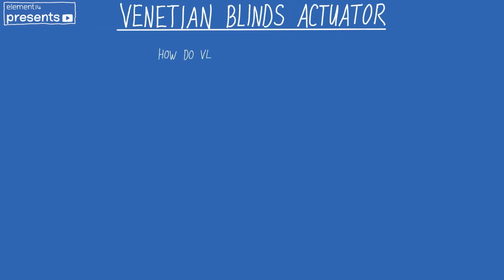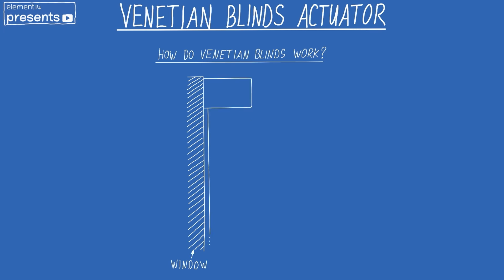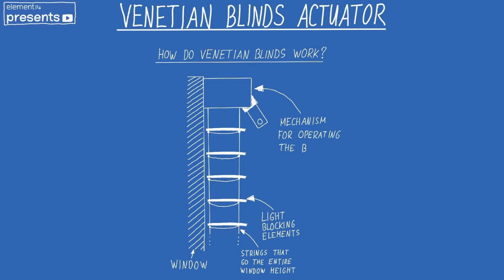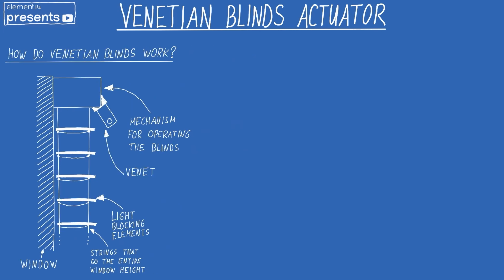So this is the first of the actuators that we need to design. This one is for the Venetians. So how do actually Venetians work? They have these light blocking elements that change their angle depending on how much you spin the axle that you see on the top here, and that's usually done with a wand. So what we need to do for our actuator is actually mount a motor that can spin it either in one or the other direction.